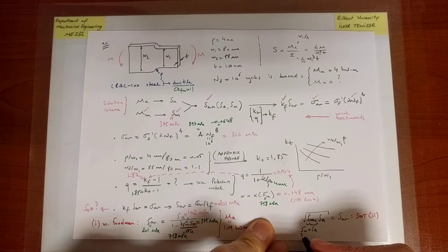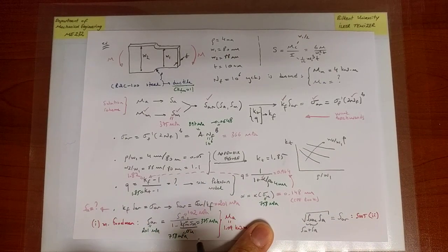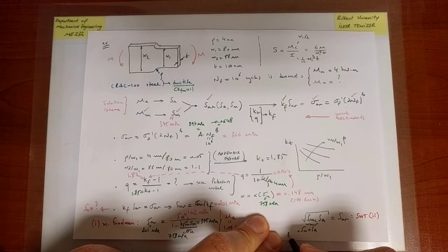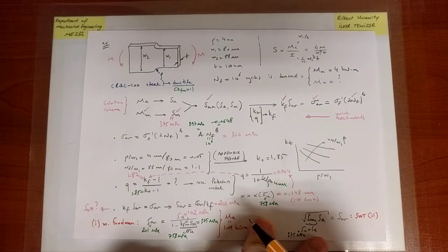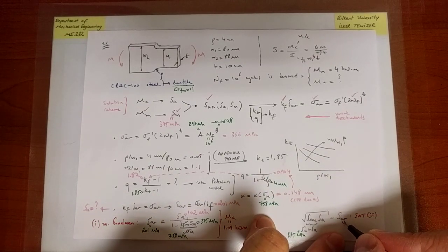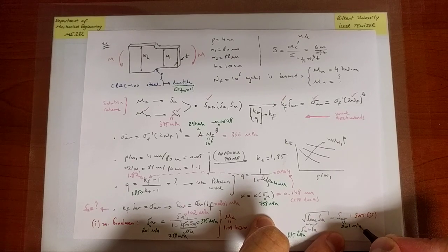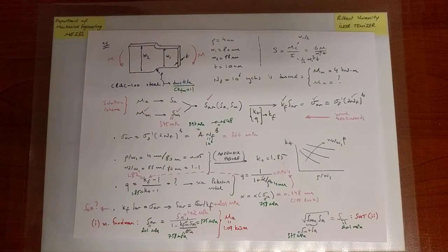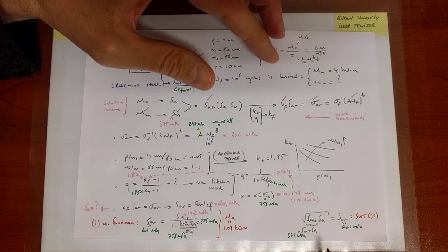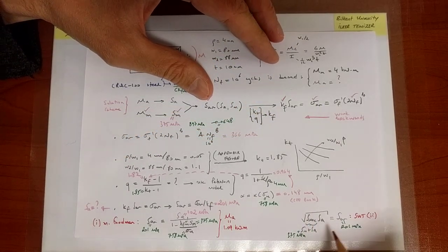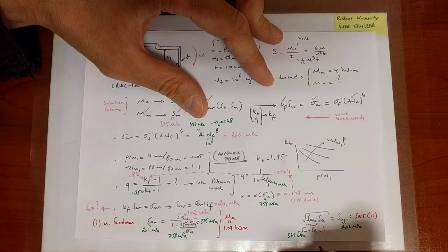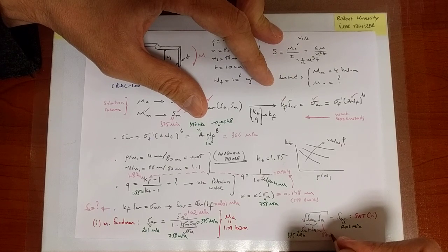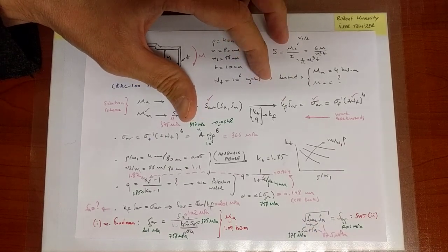And we already know the value of SM. It is given. It is 375 MPa. We already calculated it. And we know the right-hand side, we've already calculated that as well, it's 201 MPa. So there is only one unknown, which is SA. Now notice that if I square both sides, I will have a quadratic equation for SA. You can solve for it easily. The meaningful root is 87.5 MPa.